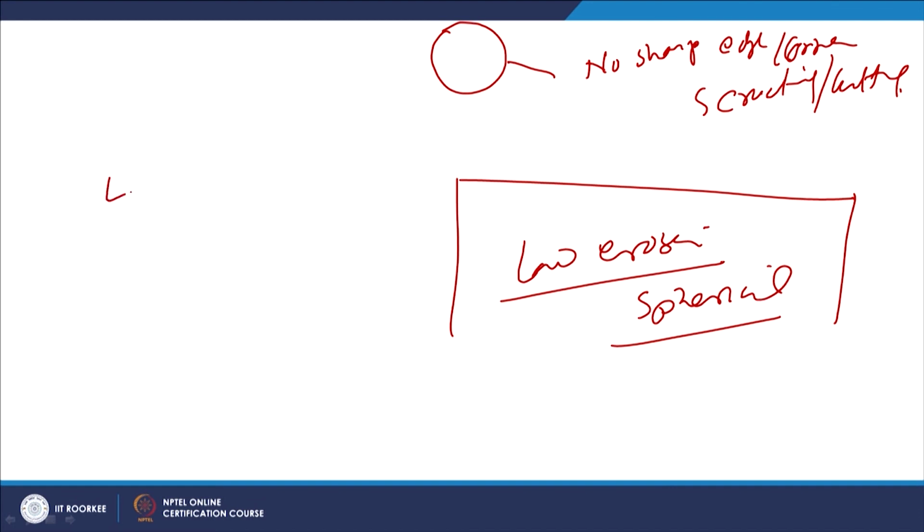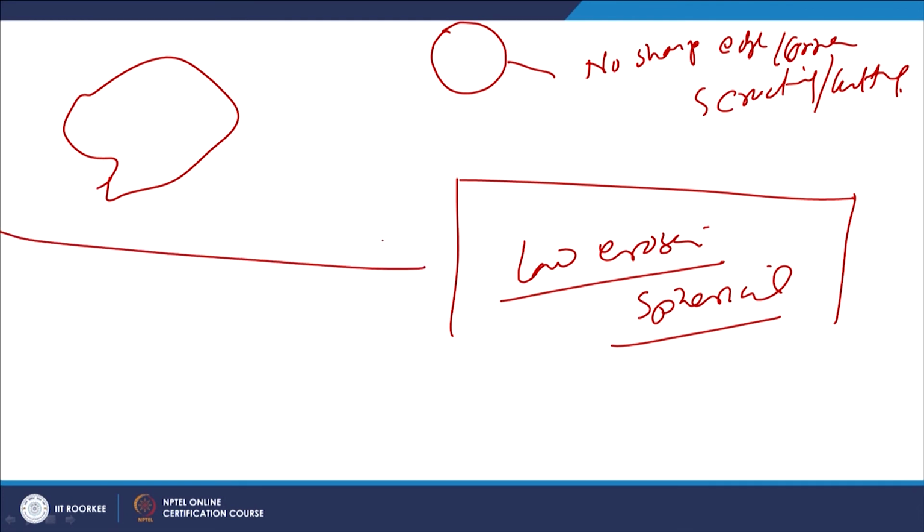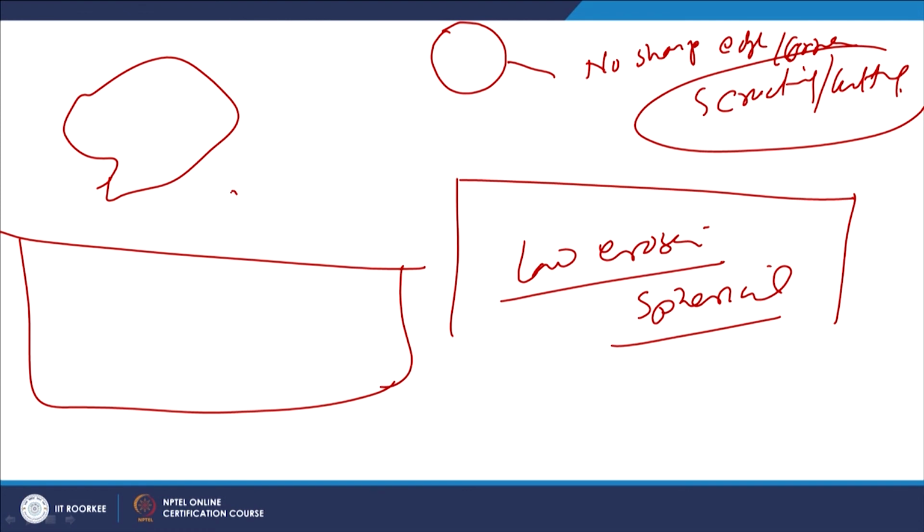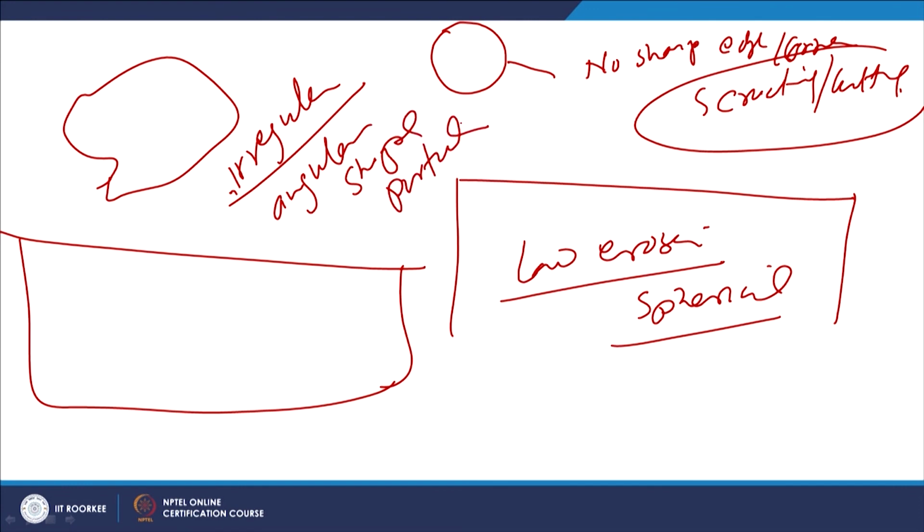On the other hand, angular particles having very sharp corners, whenever such impingement takes place, promote the scratching and cutting action. Therefore, the material loss in case of irregular or angular shaped particles is significantly greater, because their sharp edges promote the scratching and cutting action.